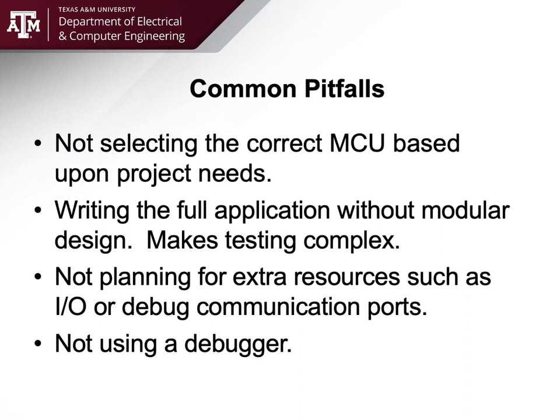Writing your full application without modular design. In other words, you just write main.c, everything is written at once. Disadvantage, it makes your testing very complex. Advantage, it's done. Good luck debugging that, because I've done that, and you quickly start cutting and pasting your code out and go back to the basics real fast.